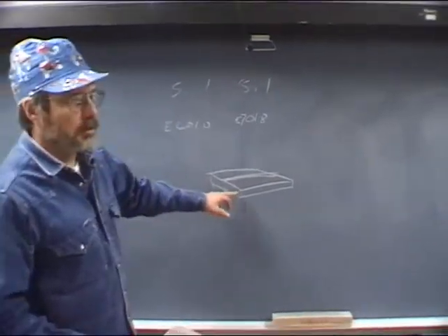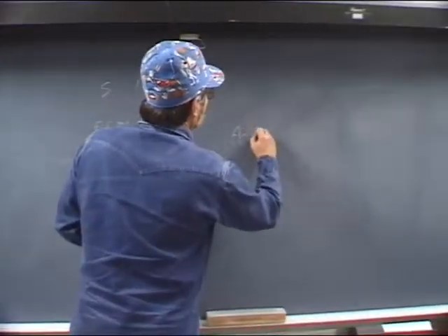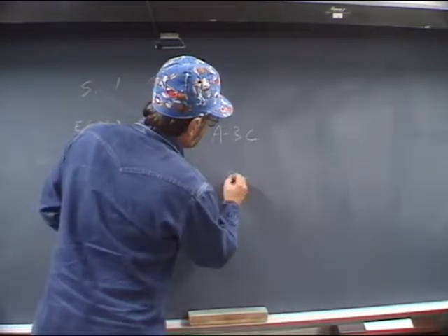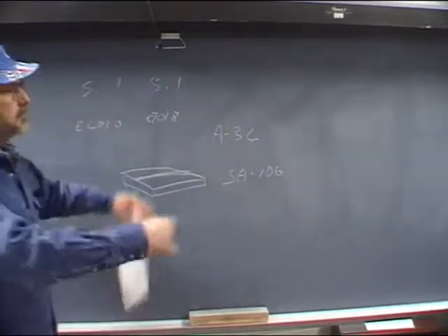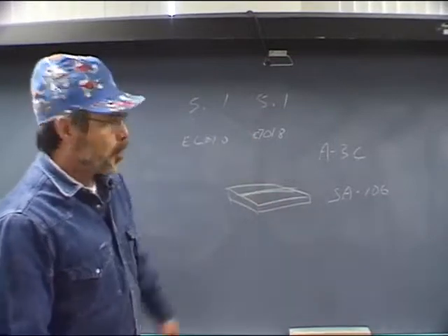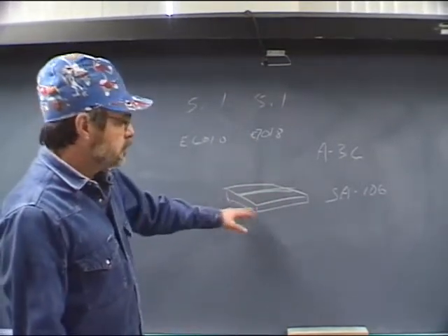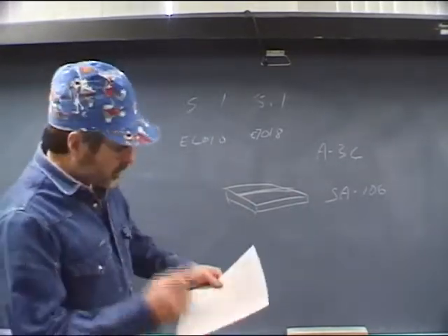But under ASME, yeah, you can do a plate qualification using A36, for example, and that would qualify a pipe qualification using SA 106, because the mechanical properties all came out of the same batch of metal at the foundry. They were just poured into different product forms, product shapes. So this proves that the mechanical properties are going to work, so you can do it with plate under ASME.